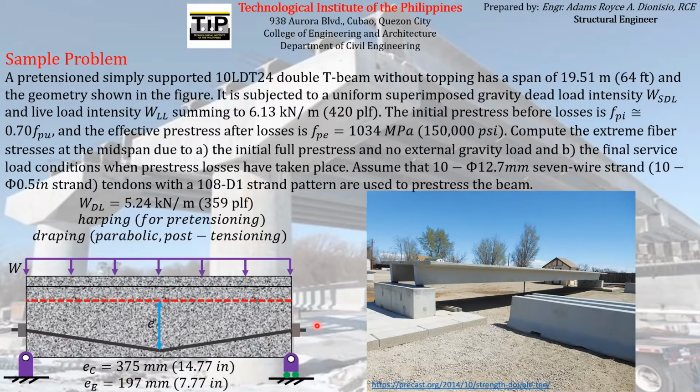after the pre-stressing reinforcement is jacked, after some time, after the concrete element has already attained enough strength to resist the compressive force that will be imposed by the pre-stressing reinforcement, the pre-stressing reinforcement will be cut, thereby exerting a compressive force on the concrete element due to the fact that it tries to go back to its original length, because we all know that the pre-stressing reinforcement in this circumstance is already elongated.